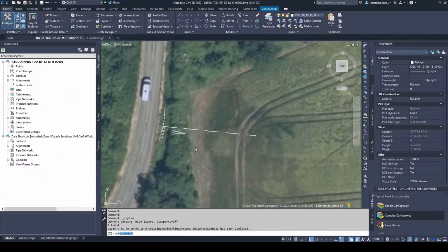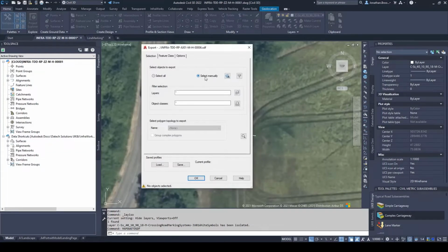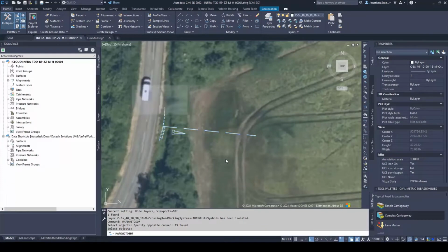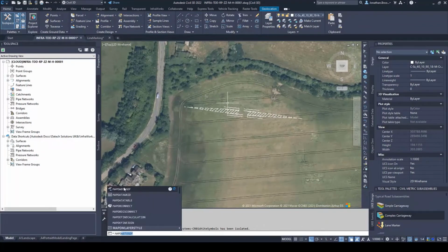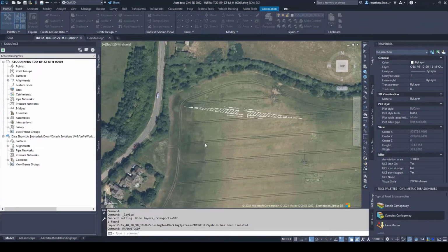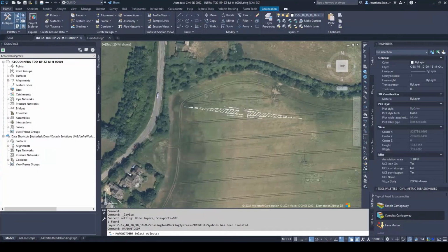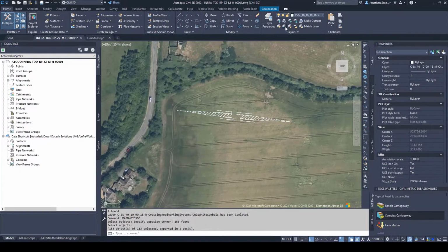Further to the application of shapefiles comes the addition of spatial data files or SDFs. For infrastructure type projects, or indeed the civil aspects of a building's projects, spatial data files allow us to include further context to our InfraWorks model. It means that we can include our line marking designs, which have been accurately set out and dimensioned on the 2D plan, as an overlay in our 3D terrain inside our InfraWorks model. Like shapefiles, we can export this information from Civil 3D, only this time using the map DWG to SDF command.